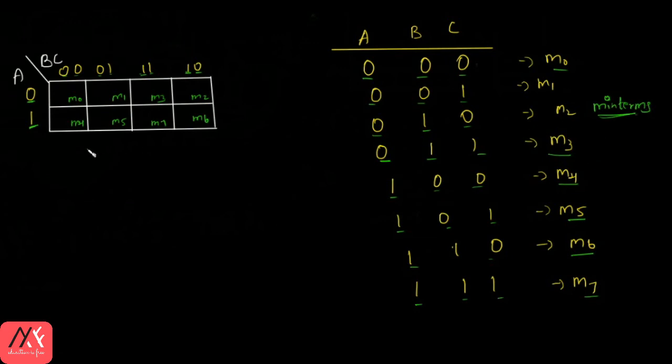Right. So let's see how to solve the groupings. So M0, M1, in some textbooks they will be giving 1, 2, 3, 4. Right. So we'll go with the grouping. How to form the groups. For example, if there is a prime implicant in M0 and there is a prime implicant in M1, and there is one in M7 and M6, right? So all you have to do is to group them like this, right? So name your groups.